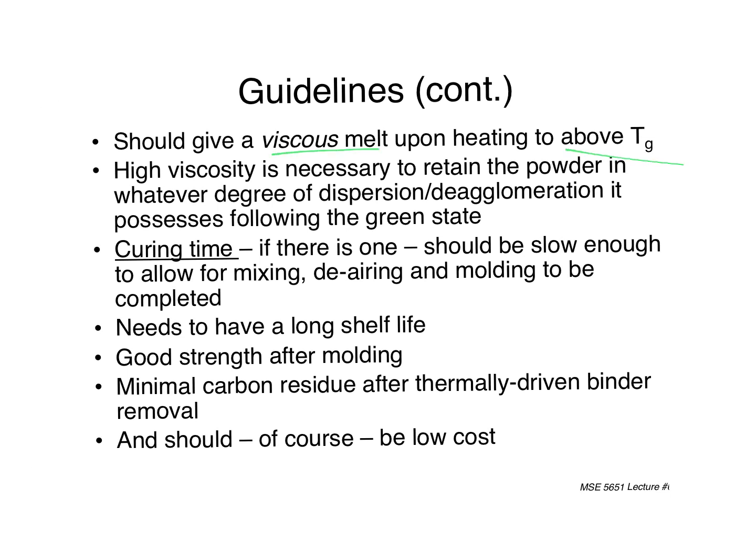And so in general, everything together, this soup of different polymers, you want it to give you a viscous melt upon heating to above the glass transition. Let's see, some of you know what a glass transition is. Are people reasonably comfortable with what glass transition is? I hear about it with glasses, but this is not really an inorganic glass. So glass transition is the temperature at which polymers become soft. Okay, and so if you take a polymer and put it in liquid nitrogen and drop it on the floor, most times it will shatter. All right, that's because it's below its glass transition. And so what we're doing in this context is we're heating things up and getting them to flow. And it requires that they not be brittle, and that's the glass transition. We go into a lot more of it with the polymers, guys, but that's the gist of it.